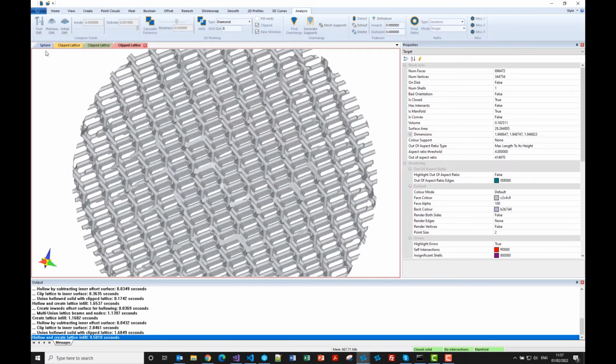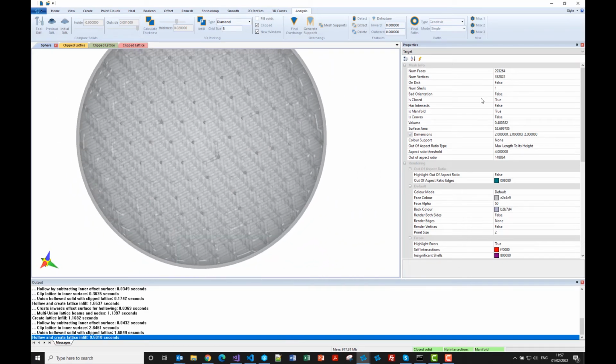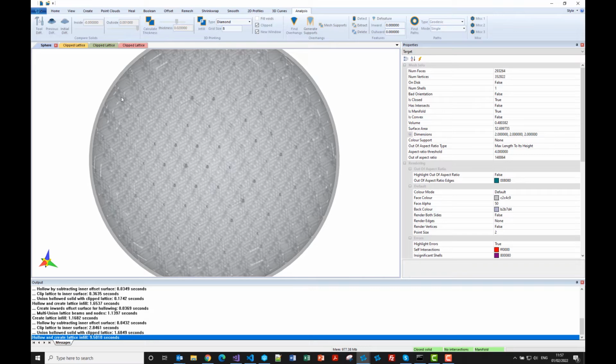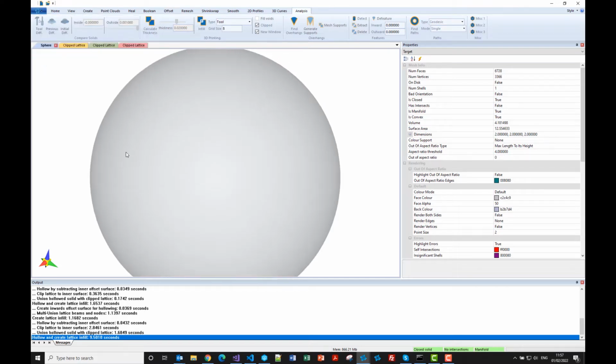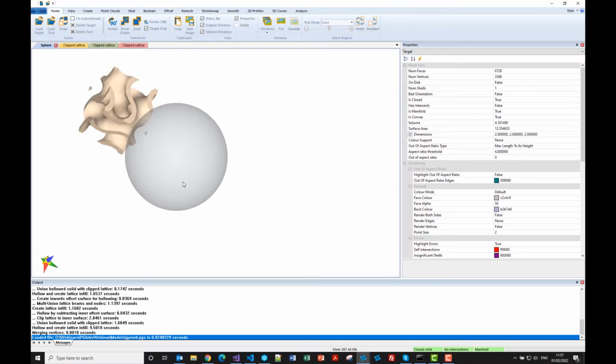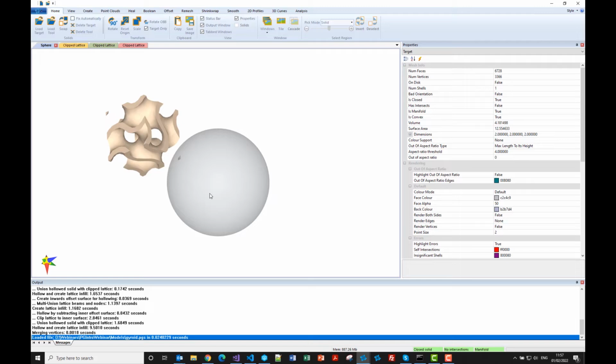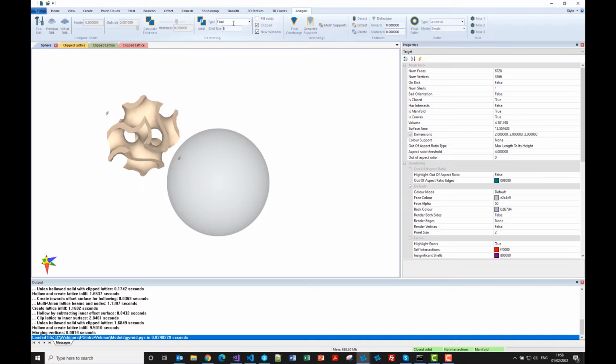I mean, that took 9.5 seconds. So very quick, and there it is inside the sphere. And again, you can see this is one shell, so it's one single solid. And finally, I will try the tool solid. So let's just undo that. I've not written any code to create a gyroid. I've just got a nice gyroid model here. So there's my little cuboid gyroid model, and I'm going to use the same principle, just repeat that 8 by 8 by 8. So tool and infill.